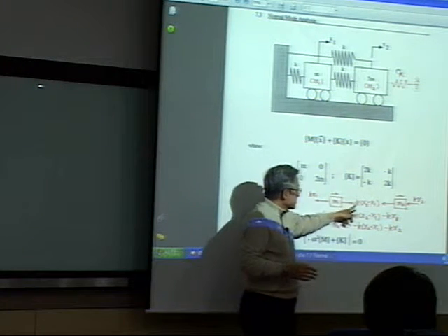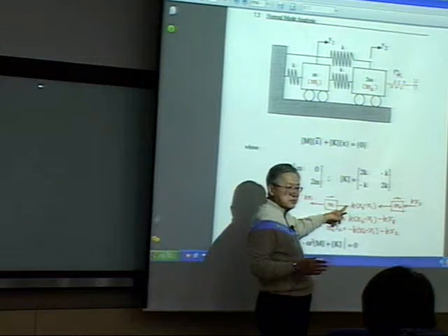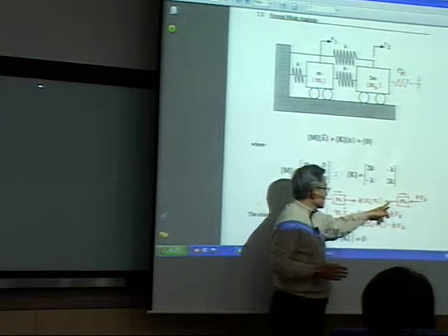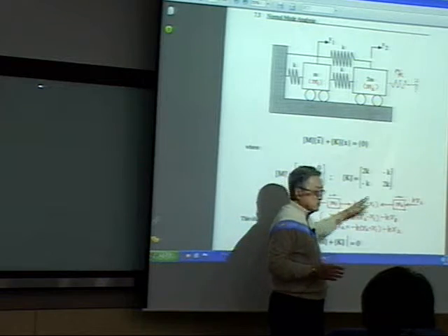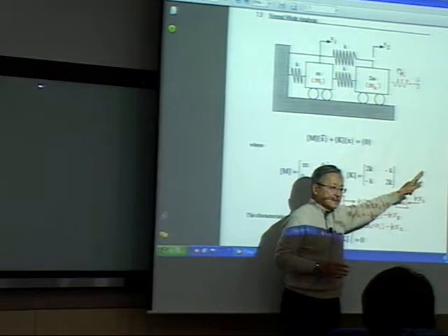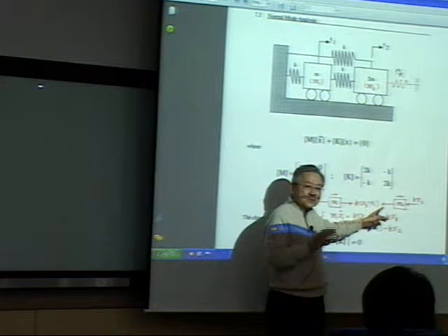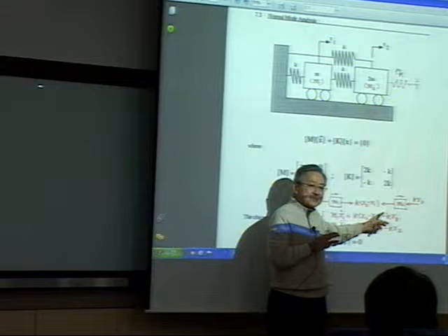So that's what this case is, in that direction. And also when you cut it, this is equal and opposite. Otherwise it will fly away. So it's going to be equal and opposite. When you set up the free body diagram this way, you will never screw up.